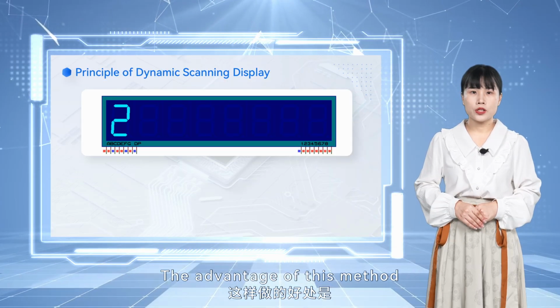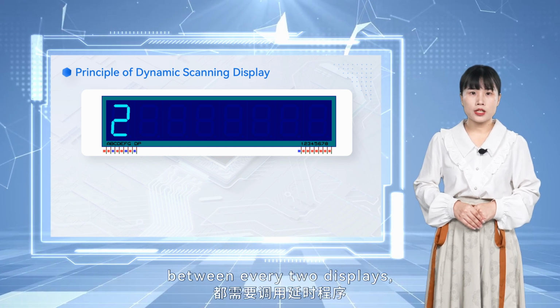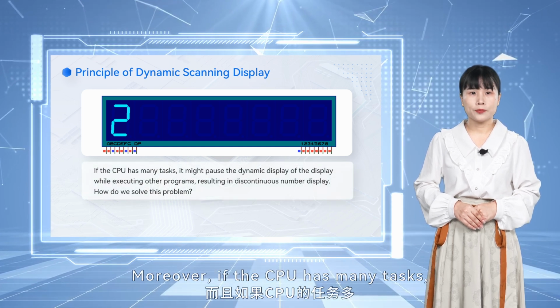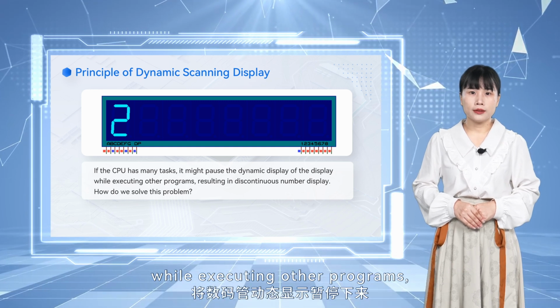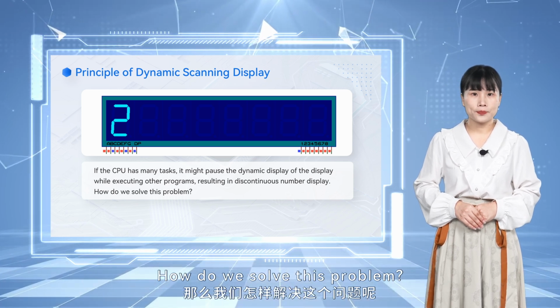The advantage of this method is that it easily achieves dynamic display. However, a delay program needs to be called between every 2 displays, which reduces the efficiency of the CPU. Moreover, if the CPU has many tasks, it might pause the dynamic display of the display while executing other programs, resulting in discontinuous number display. How do we solve this problem?